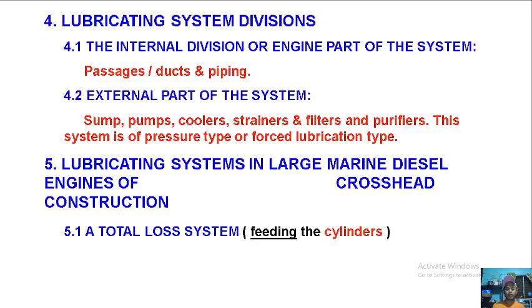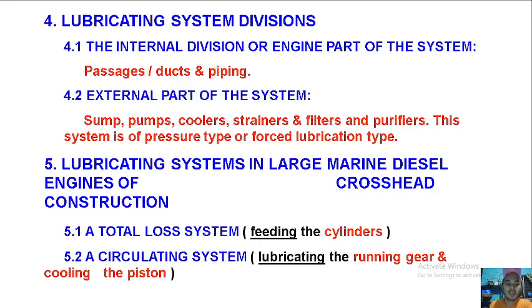Since our fuel has sulfur and vanadium, to prevent corrosion, high temperature corrosion and low temperature corrosion, we also use the cylinder lubrication in that way. It is also used in feeding the cylinder, so it will be lost during combustion also. And the next part is